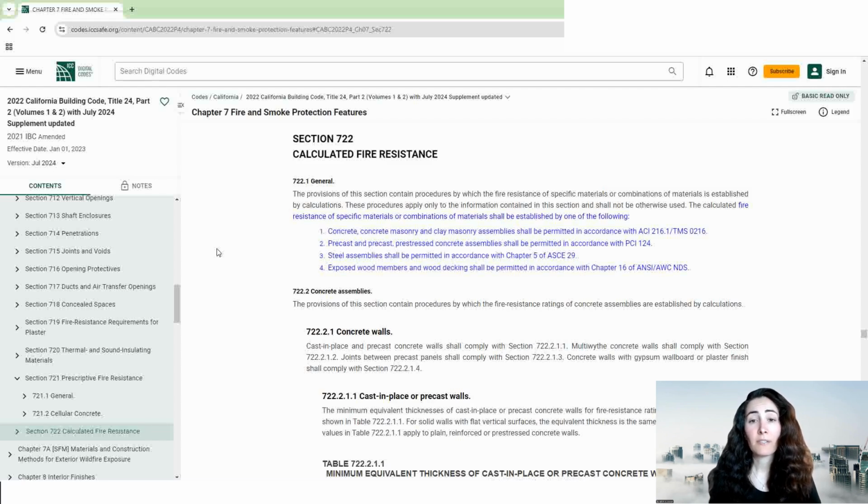They are designed to facilitate how to design and document fire assemblies so the designer and the AHJ can have some level of assurance of the performance of the calculated assembly under actual fire conditions. The formulas are based on data for heat transfer in structural members, thermal conductance of insulating materials, conduction in materials, fire test data of the fire resistance of various building materials, both individually and together, and the anticipated loads on these assemblies.